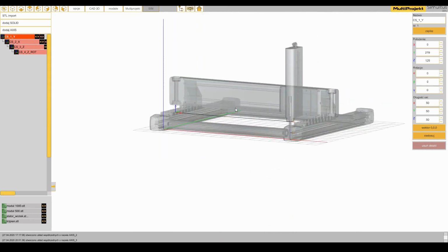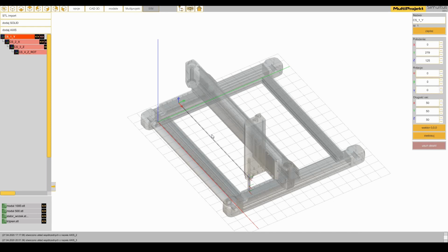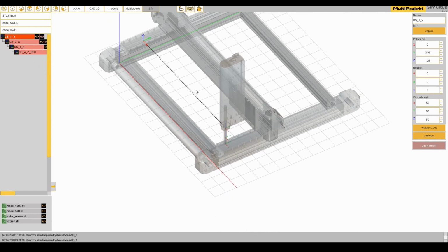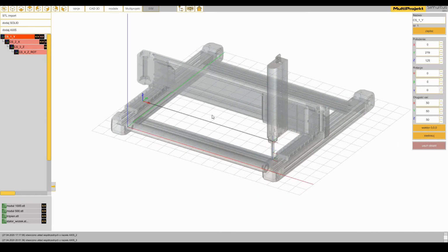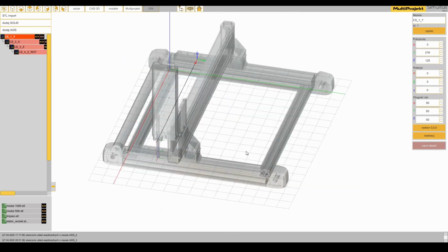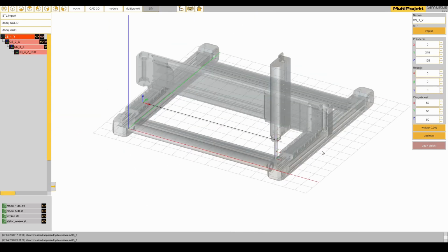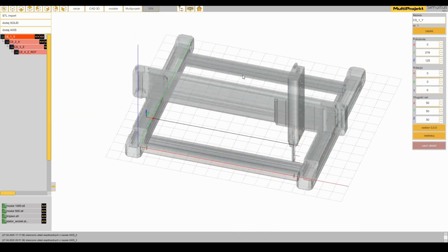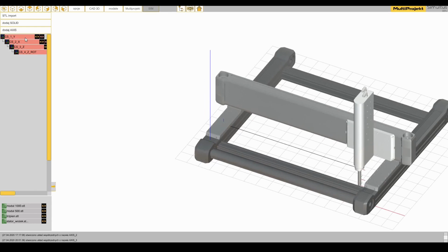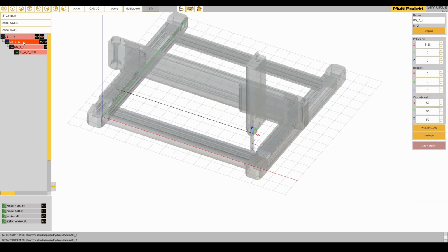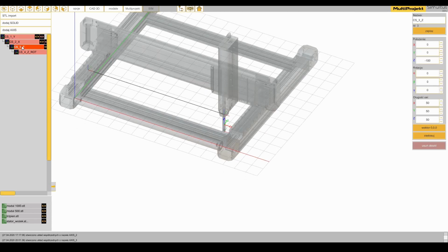If all our coordinate systems are already in place, we can now attach to them the mechanical elements that make up our device. In Simultus, moving solids involves moving the coordinate systems to which they are connected. Therefore, if we want to move a solid, we must connect to it the selected coordinate system and move it. We connect solids with systems in the same way as we establish connections between systems. We simply drag the solid into the appropriate system using the drag and drop method.